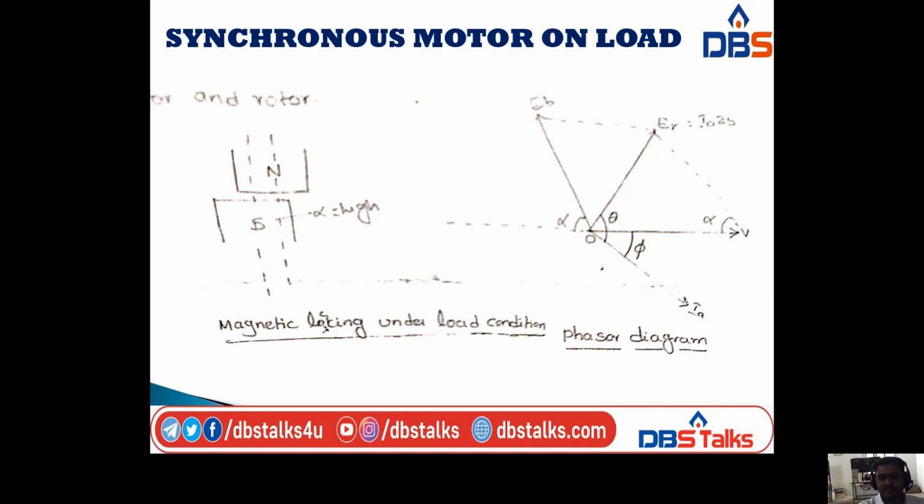So this is the diagram to explain the magnetic locking under load condition, and this is the phasor diagram we are taking. Here we have the losses, that is Ia Zs, the synchronous impedance drop. Here I am taking the voltage as a reference phasor, and Ia lags V by angle phi, leads the back EMF at an angle alpha, and leads ER with an angle theta.